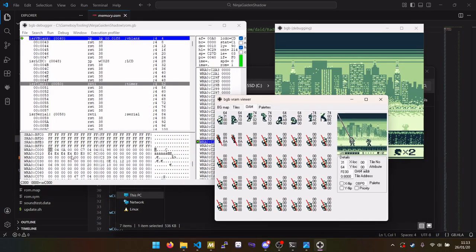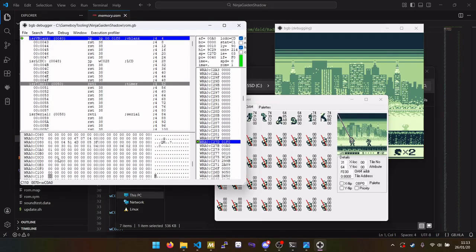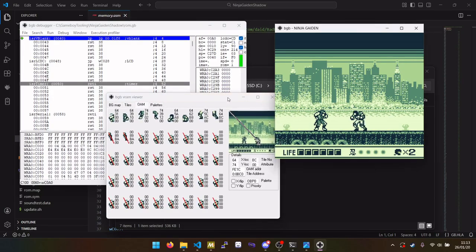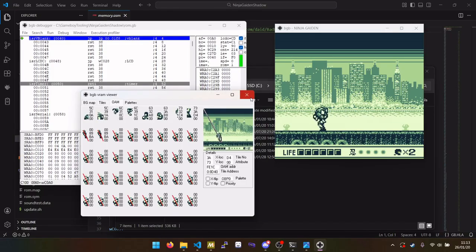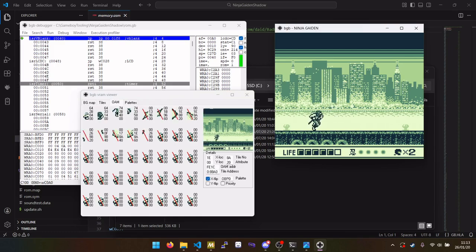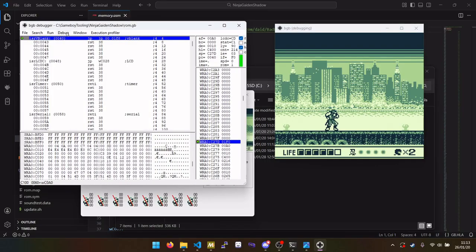So here I quickly look if I see the OEM shadow memory, but I don't directly spot it. It's usually at the first address in work memory, and it is not for this game. So I don't dive more into it, because if it's there, it's good, but it's clearly not there. There's some other data there, because you see some memory values changing.